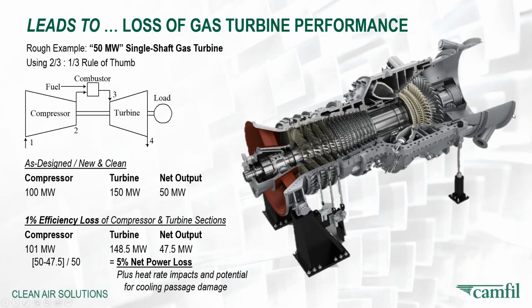Loss of gas turbine performance. We're going to give you a rough example from a 50 megawatt single shaft gas turbine. And we're going to use that 2/3, 1/3 rule of thumb, being that the compressor section, which we see over in the left-hand side of the simple graphic, will take approximately 2/3 of the power which the turbine is making. So let's look at the first set of data there, the as designed, new and clean machine. That compressor will take approximately 100 megawatts. The turbine makes 150 megawatts, leaving a net output of 50 megawatts.